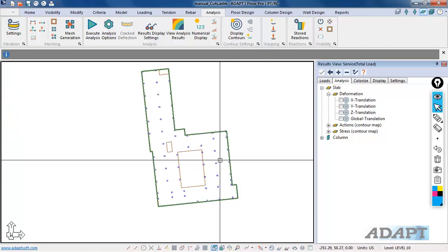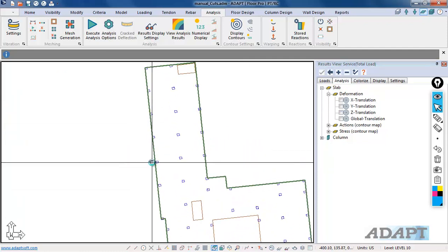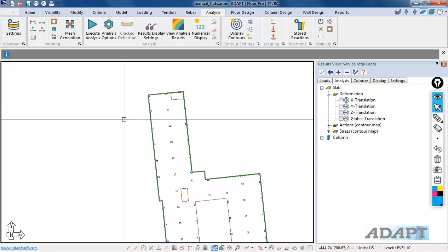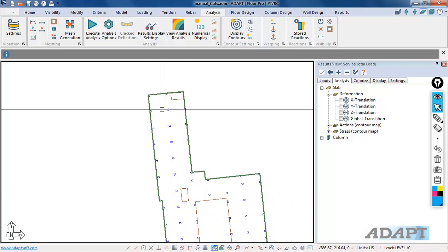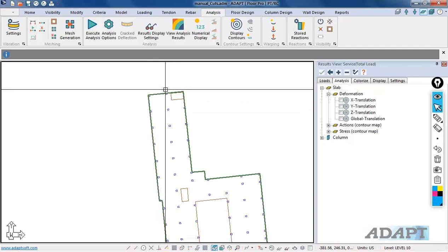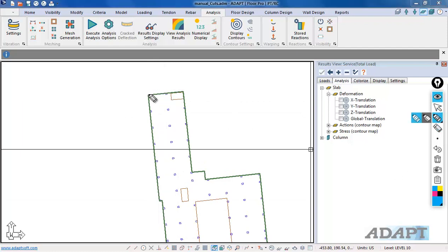We're going to clear the results there. And we're going to add some PT. We're going to, again, focus on this area. We're going to assume we have some post-tensioning. The banded direction we're going to say is along this line, and then the distributed direction might be along this line. So we're going to add a few post-tensioning cables here, and we're going to terminate one of the bands. Will terminate at this edge. The other band, we're just going to bring that down and anchor it here. The same thing, we'll anchor that there, and then we'll just add the distributed cables in this location.